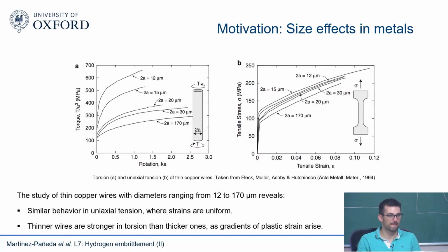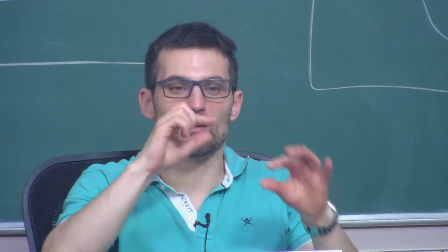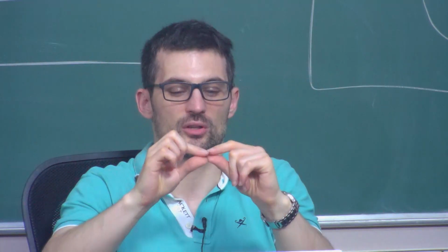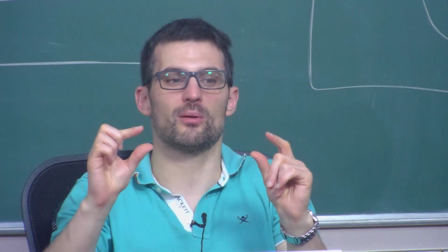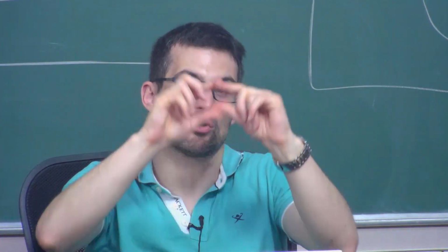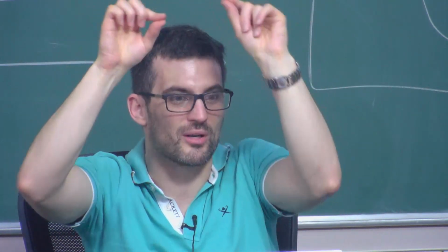In the case of bending, you do see it, yeah. If you start bending thin foils, a lot of people have done experiments on very thin foils of nickel and other materials. With thick foils, no problem. You start lowering the foil thickness, then you see this. If you normalize the moment, you get a very rising moment eventually when you get to very thin foils, because you have gradients of plastic deformation, and you need to accommodate those GNDs.